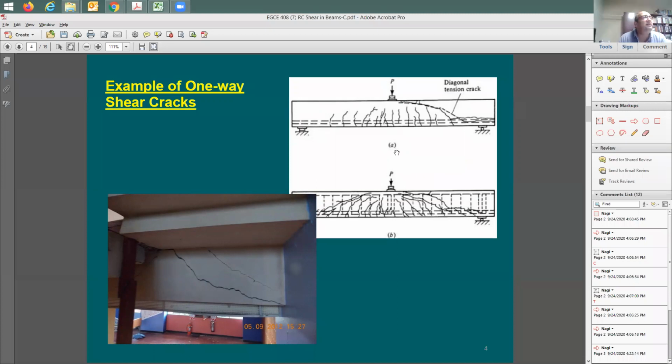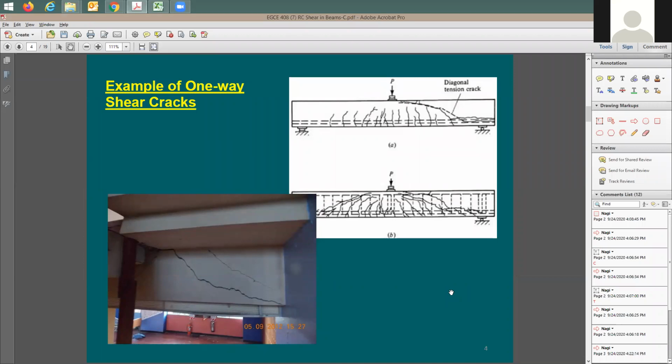You need to take the tiles away and look at the beam and see if you have any cracks at the bottom, like these cracks. You can see them at the bottom of the beam. If the beam is free from cracks, then you know that you're in good shape. There's nothing wrong with it. But once you see any cracks like this, you don't stay in the building. Oh, okay, roger that. The same thing would go for parking structures that have exposed beams. Yes. Right. Okay. Yeah, and parking structures.